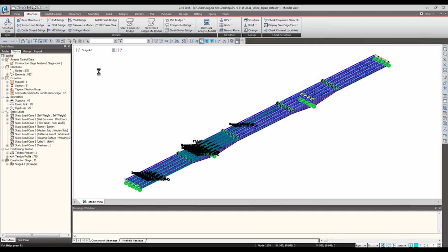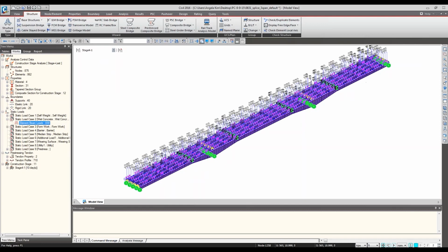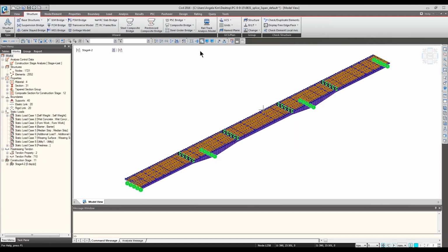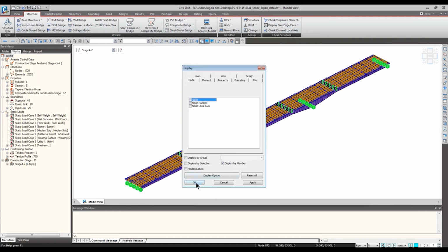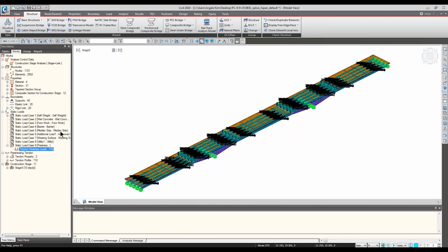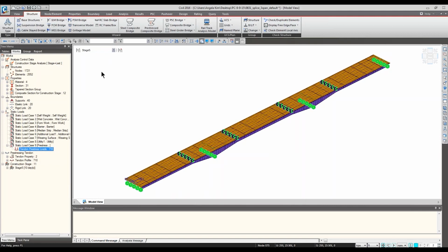You can apply the first post-tension. And then in stage 4, this is where the wet concrete is poured. And in stage 4-2, the deck is finally hardened, making this fully composite. Once this is done, you can apply the second post-tension. And also in stage 6, it's going to get rid of the temporary supports. After that, all of the superimposed dead load and live load can come in after stage 8.